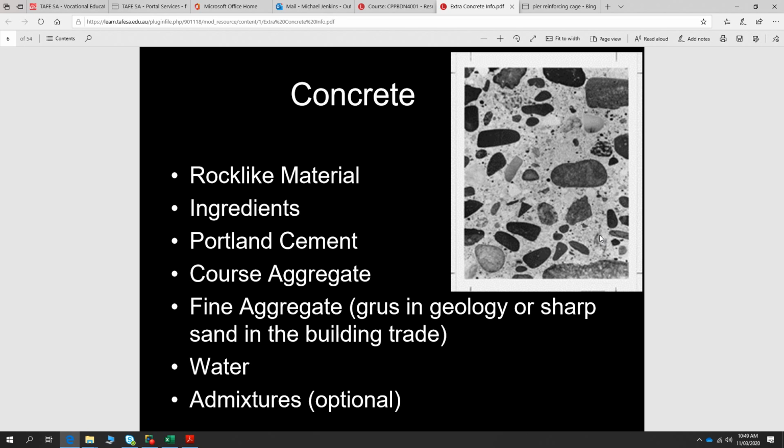It also makes it a little bit more malleable and workable, and also makes it much cheaper and much more energy efficient, with a lower embodied energy, because cement powder requires a lot of energy to produce. Whereas that slag is a byproduct of other industries. So that gets crushed up and it behaves a bit like cement. Well, it can be used as an additive to cement to a certain extent.